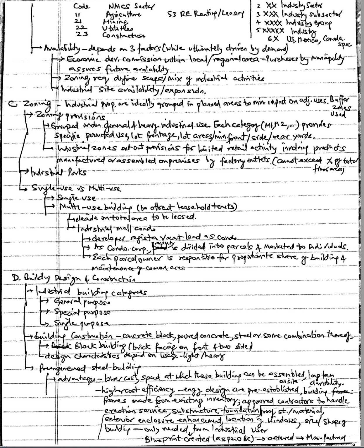Typical industrial building. Most small to medium-sized industrial general purpose buildings offer similar features and characteristics. For example, a freestanding structure typically includes both a main industrial area and an office area. The industrial area must have a single floor with a clear height typically between 16 and 25 feet, higher if required, a poured concrete slab on grade, a steel frame roof using open web joists, a built-up roof with stone ballast, steel strip windows, metal doors, and overhead doors for loading docks.